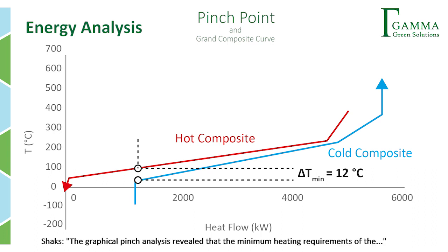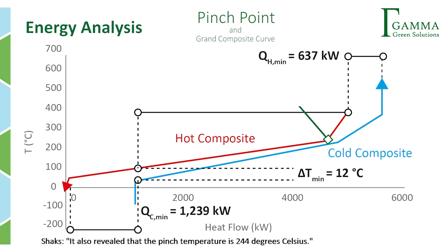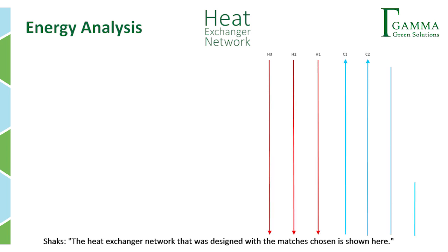The graphical pinch analysis revealed that the minimum heating requirements of the process amounted to 637 kilowatts, whilst minimum cooling requirements were 1,239 kilowatts. It also revealed that the pinch temperature is 244 degrees Celsius. The heat exchanger network that was designed with the matches chosen is shown here.